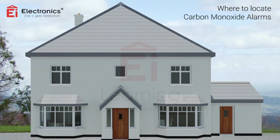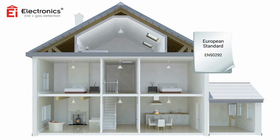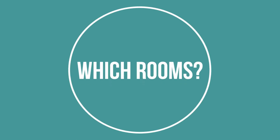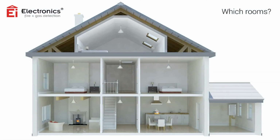Where to locate carbon monoxide alarms? In accordance with European Standard EN 50292, this tutorial gives general guidance on where to fit carbon monoxide alarms. Which rooms? Ideally, carbon monoxide alarms should be installed in every room containing a fuel-burning appliance.